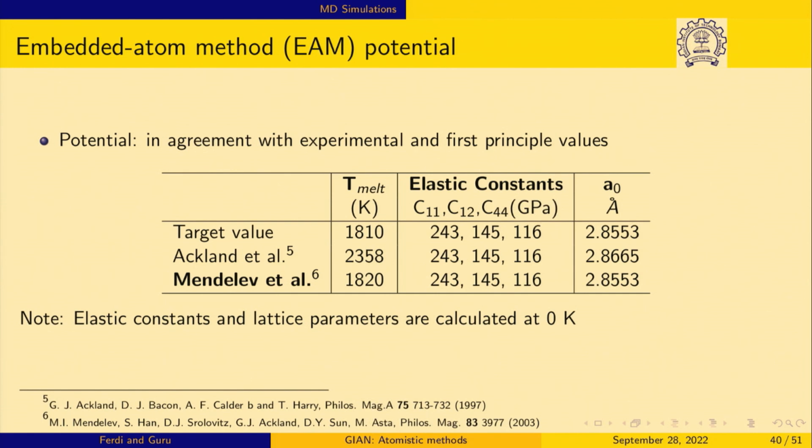So, I need to know the melting temperature so that I can establish a solid melt interface, and this temperature could be a few degrees different for 100, 110, 111 interface, and our system sizes are small. If it is 1812 and if you are taking 1808 or 1816, either the entire cell will melt or the entire cell will solidify. Okay.